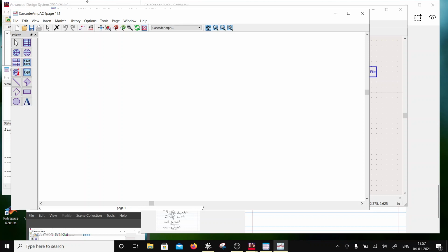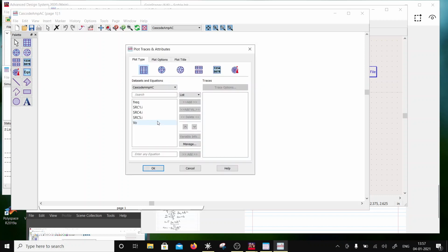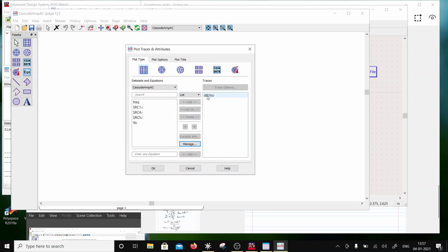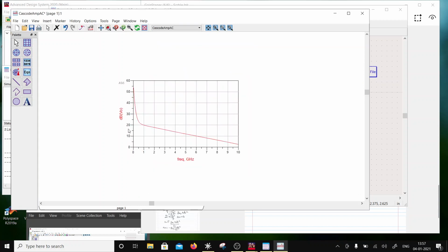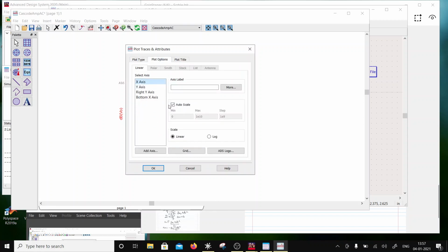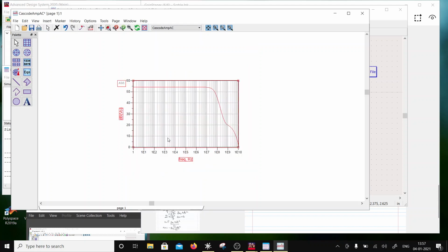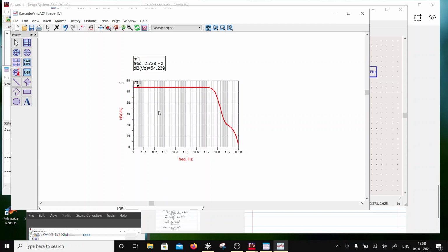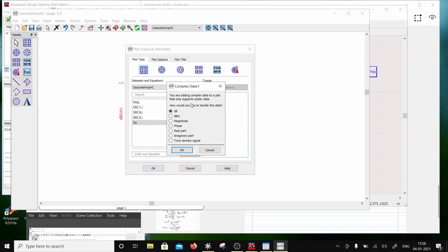What I have over here, I can plot the gain, which is going to be the dB of V out because the input is 1 volt, right? And here I am going to do a log scale on the x-axis. So here you see the gain is much higher, right? The gain is around 54 dB, so that's what you are expecting here, gm rds squared by 2, and then you are also going to put in here the phase.